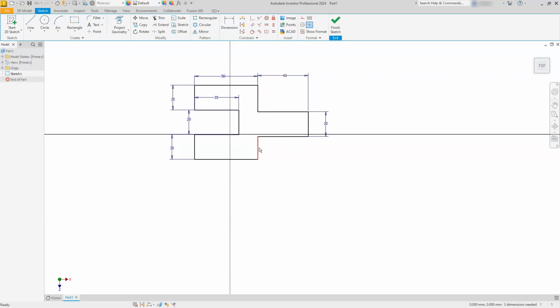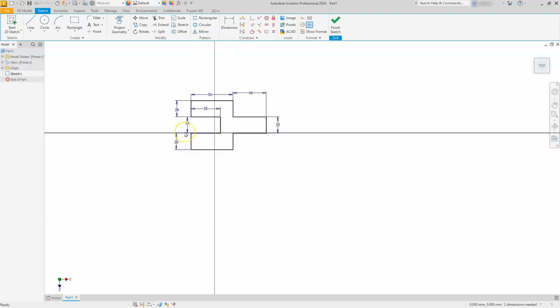Now it doesn't tell me that these two parts are in line with each other, or are the same length. So I think I can go ahead and apply that now if I wanted to. Because you can see from the drawing, I don't even have any dimensions placed on that. It gives me that this is locked at 20, so it is implied that this line here is equal to that line. So I will apply the equal constraint. So I'll go to equal, select that line, and then I'll select that line. And you're going to see that now it sets these two equal to each other. Alright, go ahead and hit the escape button.